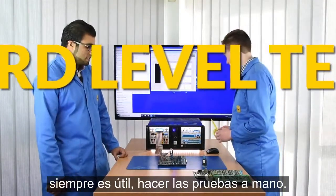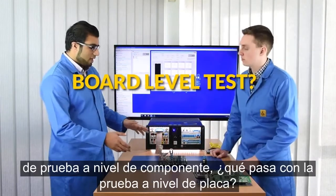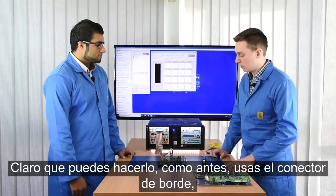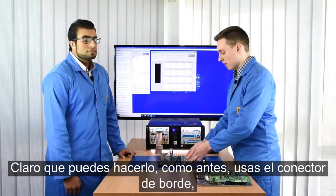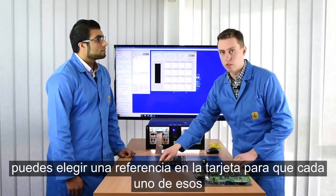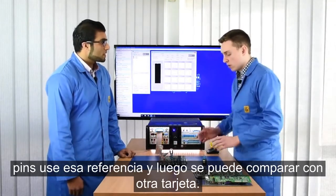I see, very interesting. So we've been talking about component level tests so far. What about a board level test? Can we do that? Of course you can do that. So using the edge connector, you can choose a reference on your board, so it can go from every one of those pins to that reference, and then you can compare that against another board.